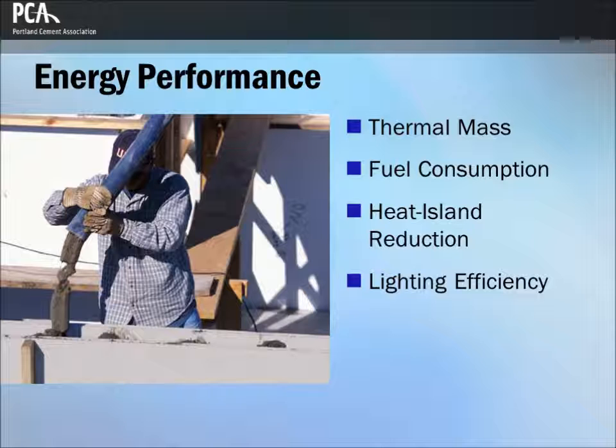Concrete structures also enhance energy performance. Concrete can enhance the overall energy performance in several applications, including thermal mass, fuel consumption, heat island reduction, and lighting efficiency. Insulating concrete forms, shown in the picture, provide thermal mass and high levels of insulation, key components for net zero energy use for structures and buildings.